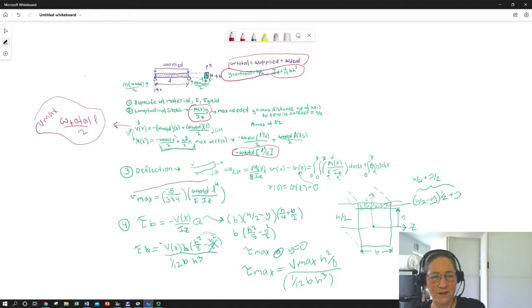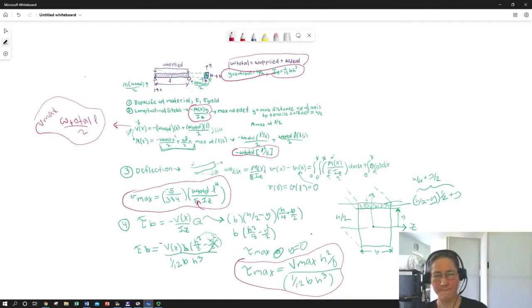My total deflection, which is the first place that I pick up something from Hooke's law for our material. And here's my max shear. Basically everything that's circled I would need to put into a spreadsheet or some kind of calculator that would automatically calculate based on something that I populated with these values: H, B, applied load.